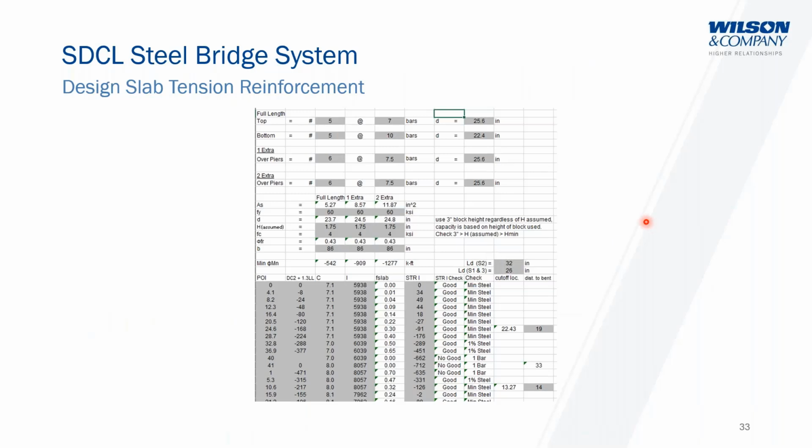And what you would typically see traditionally from DOTs, your bar patterns are either a 5-inch spacing or 6-inch spacing. Out at midspan, you're 15 or 18 or something like that, right? So like you would do with any pre-stressed concrete structure, you're going to put bars in over that support for continuity for the live load scenario.